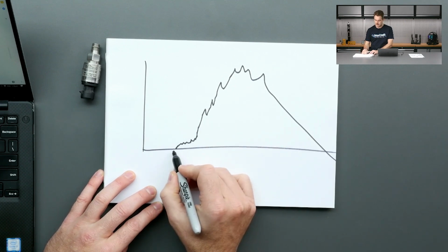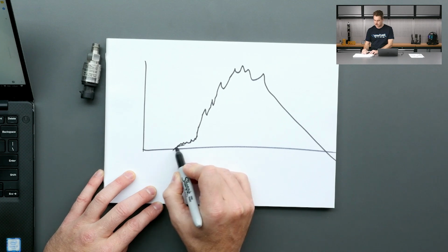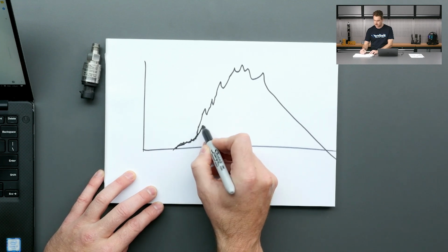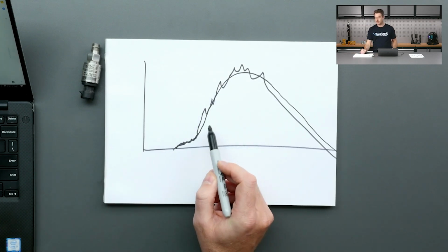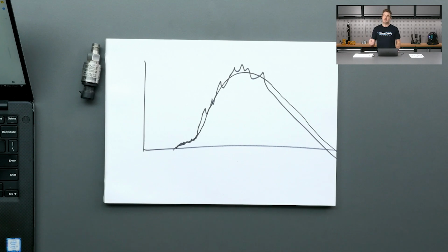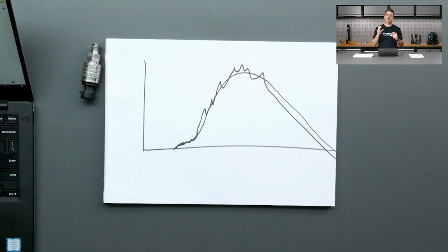What we want to do is, again, you probably guessed it, use a smooth function, and calculate the smoothed version of this with a moving average filter. Again, you've got to experiment visually with different time periods for that moving average filter. You want to find a moving average filter which calculates the guts of that shape as closely as you can, while getting rid of that high frequency noise.